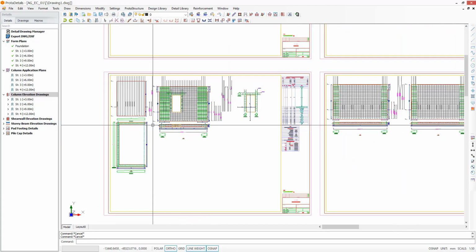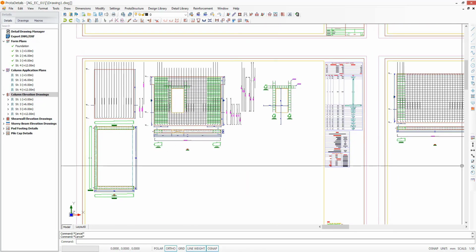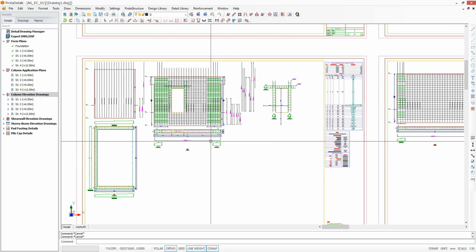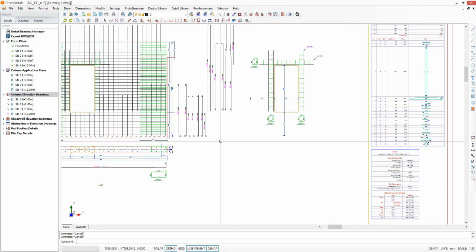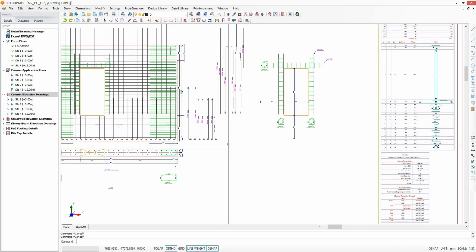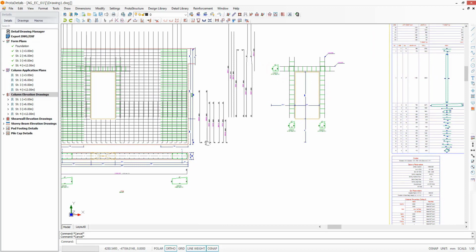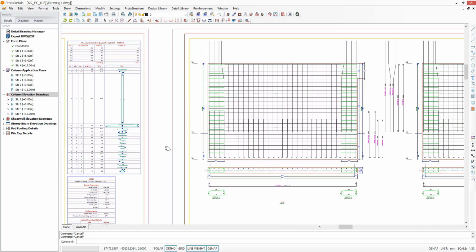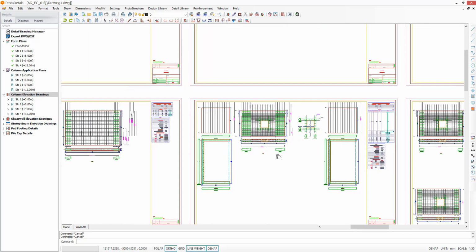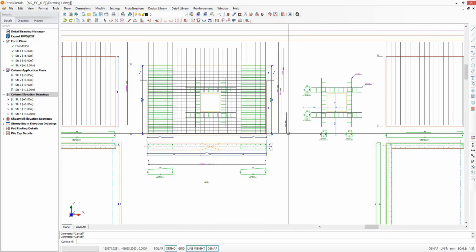Let's take a look at the shear wall details. Well, column, shear wall, and core wall details are generated with high precision. So for most cases, you won't need to edit them manually. And of course, this will save you a lot of time. And shear wall holes are displayed in elevations, detail sections, and schedules along with the required rebars. So you don't need to worry about the code-compliant hole detailing at all.